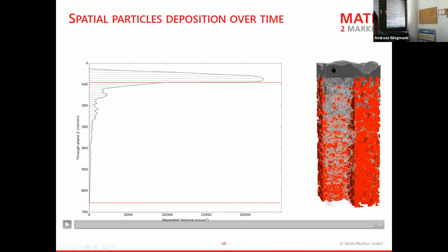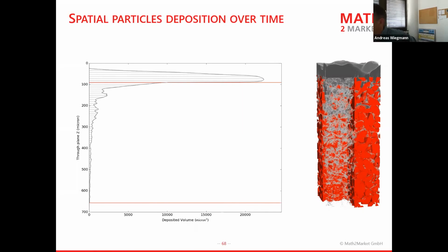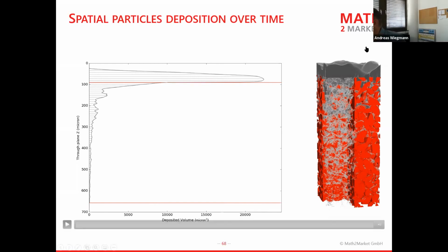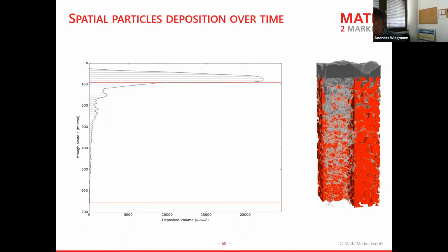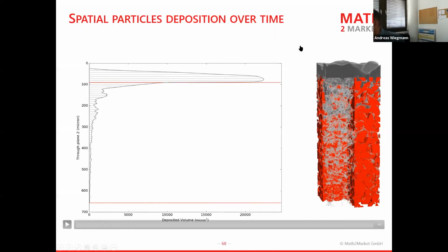in this case, soot particles, but you can add various kinds of other materials. Soot I actually like very much because we know that soot is very sticky. So from a simulation standpoint, at least you don't need to worry. Wherever it touches, it will stay on those surfaces. For other kinds of particles, you have them bouncing off again, or sometimes they stick, sometimes they don't, and then you need to model that, and you have additional parameters. So then you have to model the motion of the particles with the fluid.